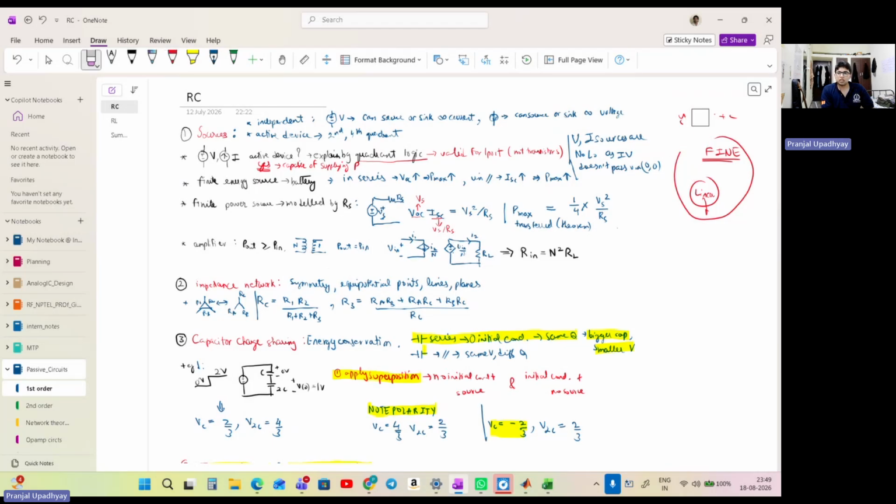And for linear, c is equal to 0. Now, just so that I can convince you why a voltage source or current source is not truly a linear system: if I express an ideal voltage source as a function of current, it is equal to a constant, right? It is equal to, let us say, Vs. Now, if I try to scale the current passing through this by A times, still the output will be Vs only, right? The output will not grow by A times.